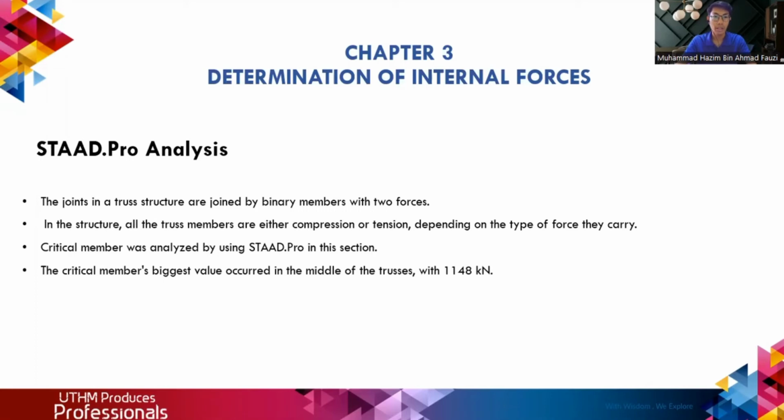In determination of internal forces, we use STAAD.Pro analysis to produce the internal forces, and from the STAAD.Pro analysis we got compression and tension. We also analyze the critical member from our truss, and we got the biggest value of the truss, which is 1148 kN.